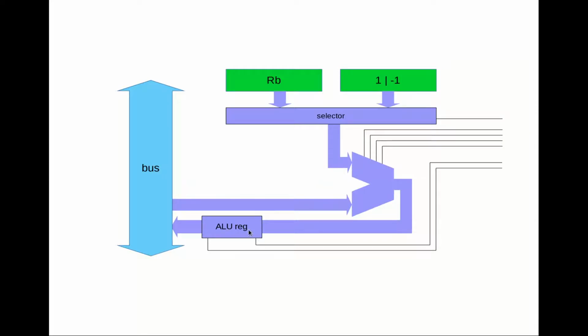So it has the result of the sum latched inside itself, so it doesn't need to write anymore. But it should then write its value out onto the bus, now that the bus is no longer being occupied by the A register. And so then the result of the calculation will be output onto the bus. And then the A register could be configured to write, or some other register could be configured to take that value from the bus and latch it.